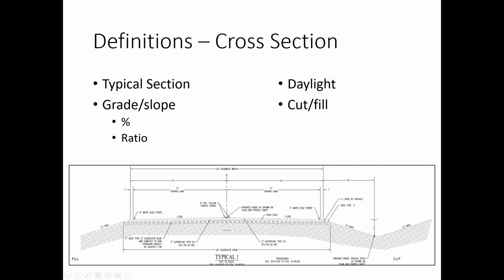So thinking about that, in the section view, a cross section, as we mentioned, is one of the main survey needs, and thinking about what a typical section for a roadway is, just to orient you to that concept. Generally, for any roadway project, engineering project, we have what's called a typical section, which is, if you took a cross section, this is what on average we want it to look like. This is the standard for which we're going to design this road.